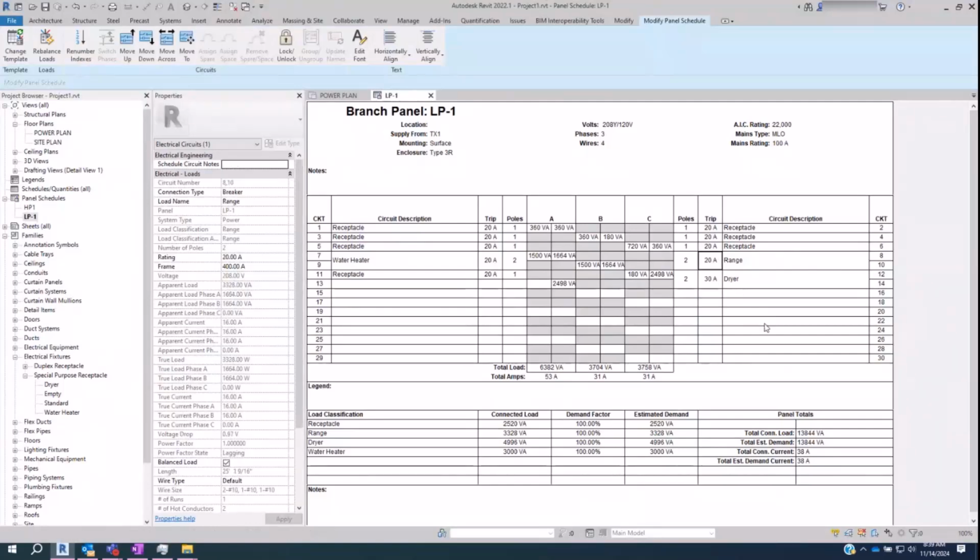Okay. All right, so yes, 30 amp breaker for the dryer. What about the range? I would assume it could probably stay at 20 because, numbers wise, it looks really close to what the water heater is. But let's do the math. 1664, divided by 208, then we multiply by 1.25. We're at 19.33. So I would say stay at a 20 amp breaker.